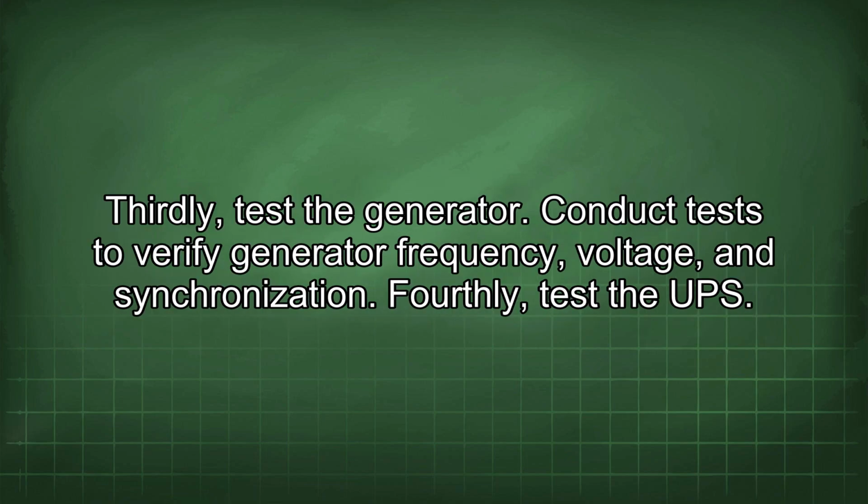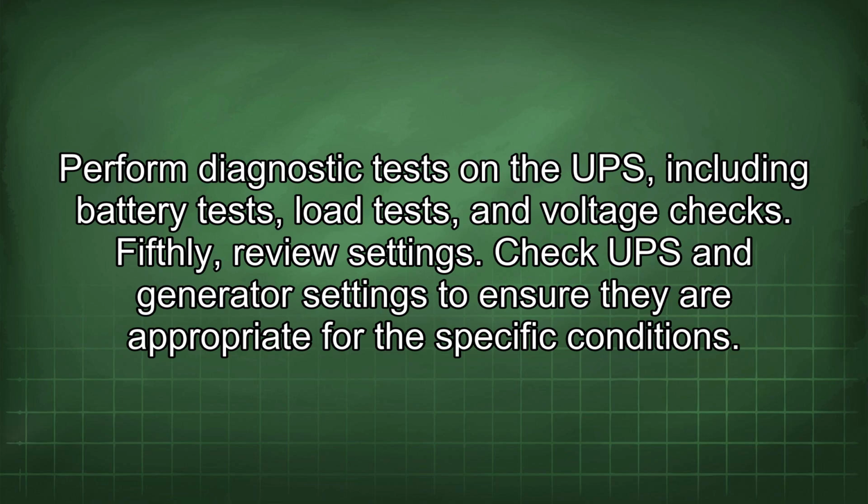Thirdly, test the generator. Conduct tests to verify generator frequency, voltage, and synchronization. Fourthly, test the UPS. Perform diagnostic tests on the UPS, including battery tests, load tests, and voltage checks.